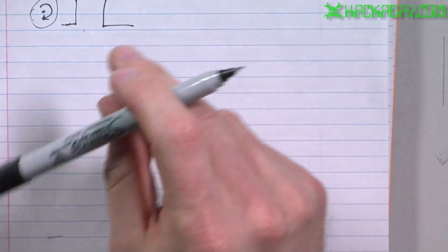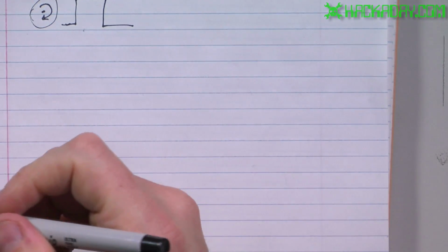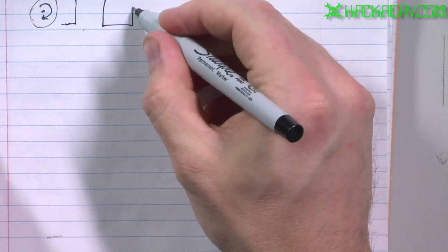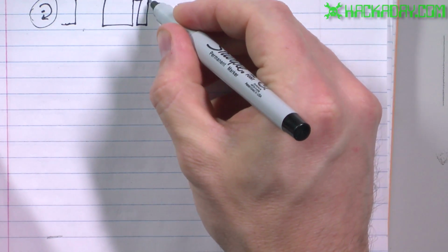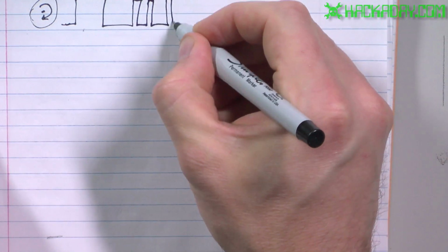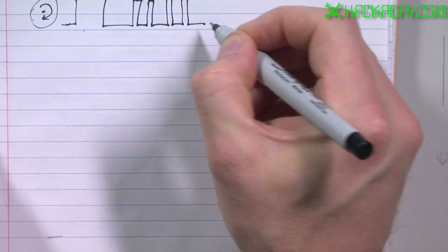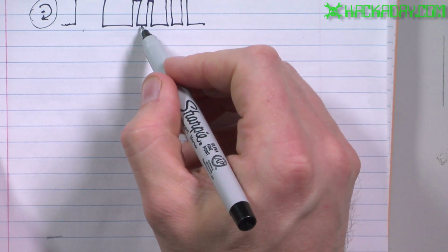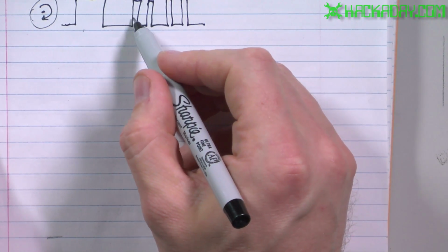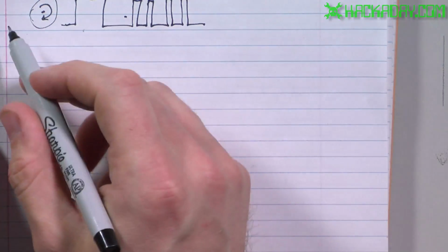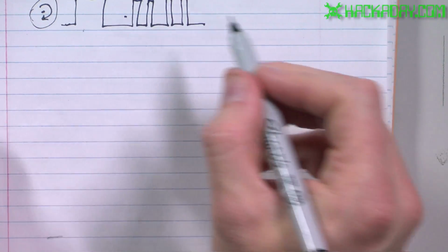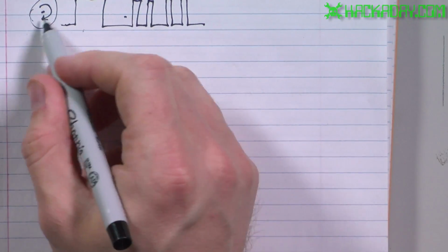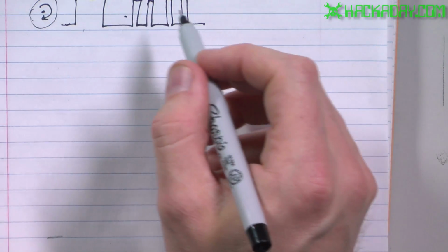What pulse width modulation does is you rapidly switch on and off whatever it is you're controlling, and the average of the on time versus the off time is what the device may see. So if it's a motor that has inductance, it actually sees an average voltage.